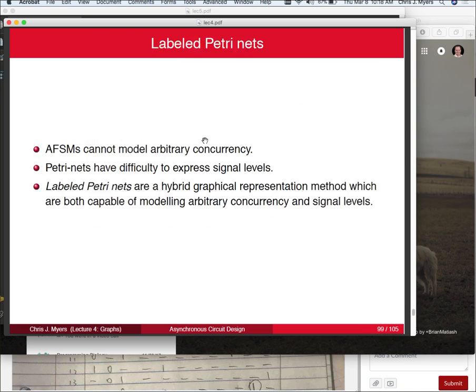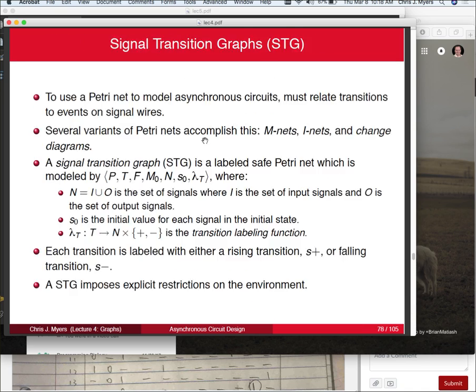So on Tuesday, I'm going to step back and talk about these STGs, because STGs, or signal transition graphs, are basically the most favorite input form for people doing speed-independent design. A lot of the software tools that do Muller circuits or speed-independent design use STGs as their input form, just like in Huffman design, the most common and favorite input form right now is burst mode and extended burst mode.